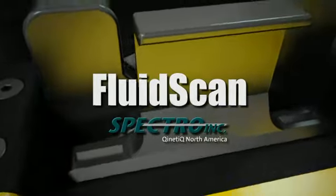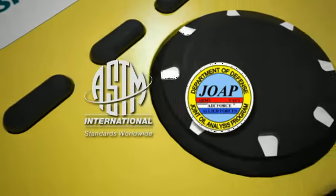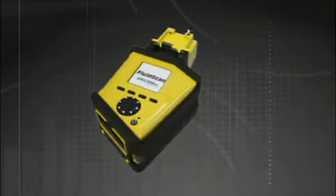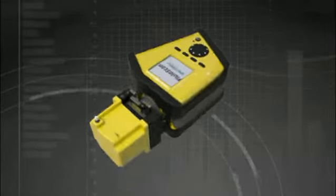FluidScan is a handheld condition-based maintenance system that delivers fluid condition assessment based on the American Society for Testing and Materials and the Joint Oil Analysis Program standard practices. It protects machinery by determining when a lubricant needs to be changed due to excessive contamination or degradation. FluidScan does this at the point of use by measuring key oil condition parameters in both synthetic and petroleum-based lubricants and fluids. FluidScan is applicable to any mechanical system where unexpected downtime is unacceptable.